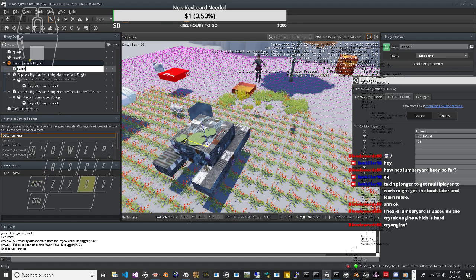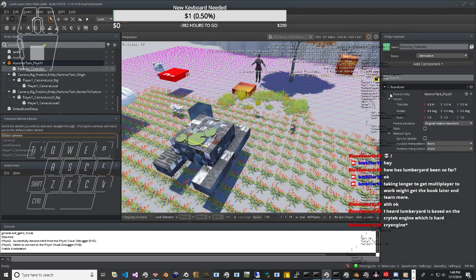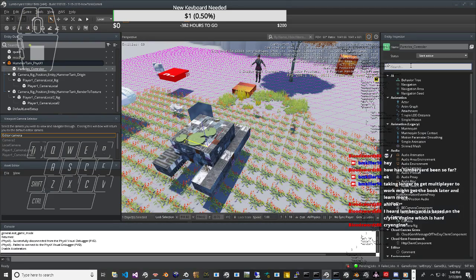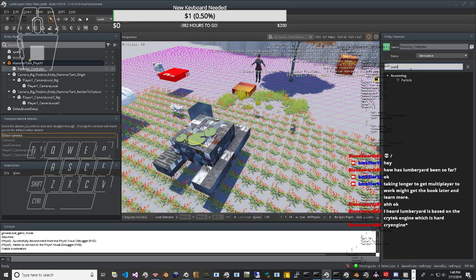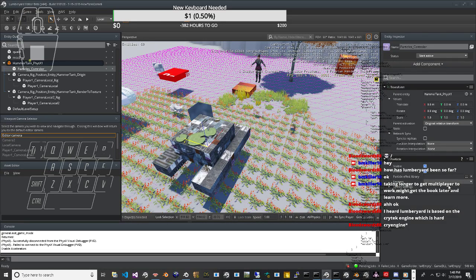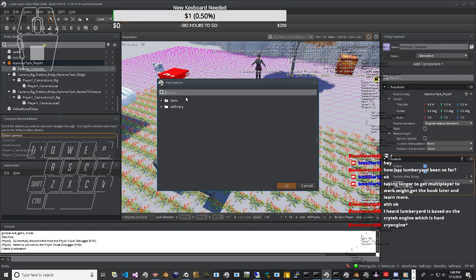As with the longitudinal magic formula, there are lots of zeros in this particular sample case, but let us not confuse particulars with generalities. The formula can account for much more general cases. The first helper is the peak lateral friction coefficient, μp = A1 Fz + A2, measured in inverse kilos if Fz is in kN.